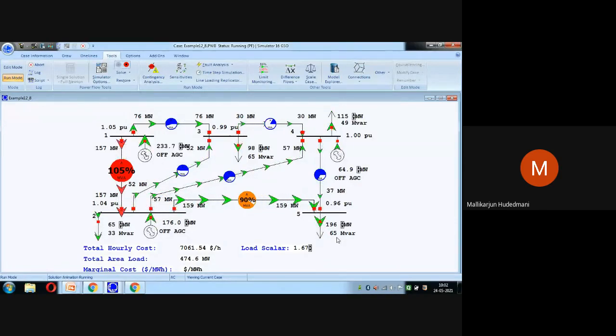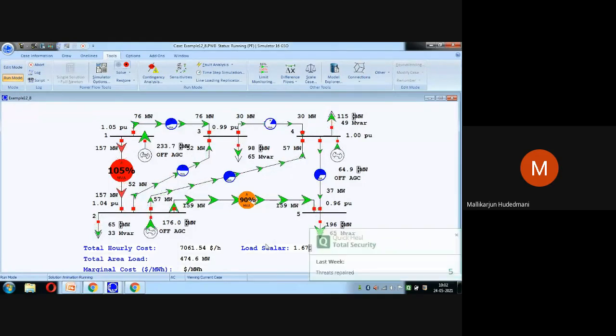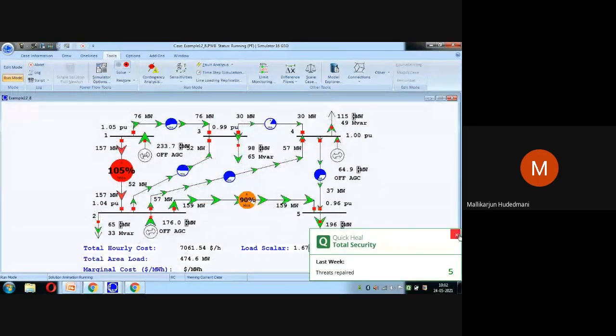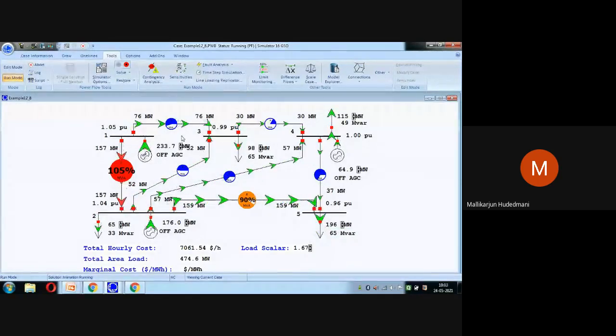So this shows you how the effect of the automatic generation controller works in practice. This simulation surely gives you the knowledge that a great deal of study is required for automatic generation control. A lot of mechanism, technology, and economics is associated with it, because it is very important from the perspective of resources and balancing the load from the end user's perspective. So I have just tried to show you how AGC being off matters, and how the swing bus matters in meeting the requirement.